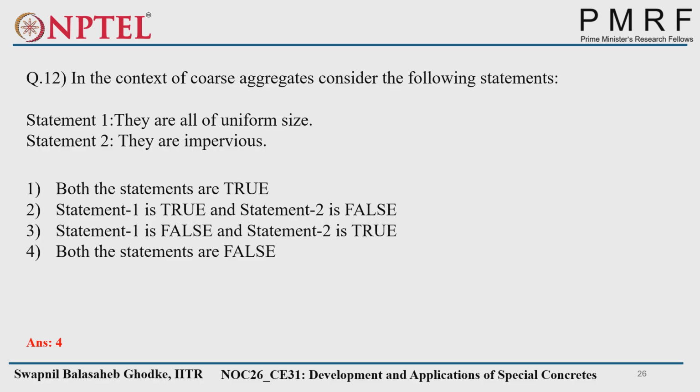Yeah, it absorbs water. That's why, as you've heard, most of the time when we are considering rheological studies, we use the aggregates in a surface saturated dry condition.